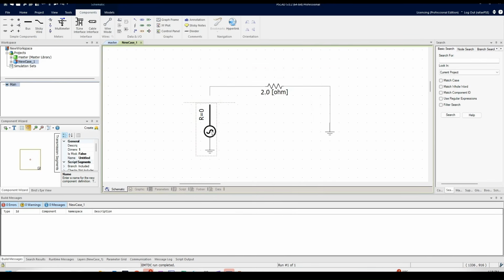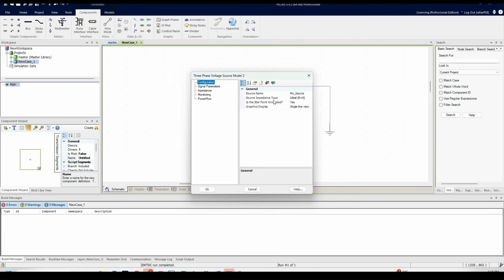And now that single phase line understands that it's connected to a three-phase system as well. It becomes important at one point because there are scenarios in PSCAD where you want to simulate a single line to ground fault, so the fault is only occurring on a single line. So it's interesting. In those cases, you do need to split up a three-phase wire into single-phase wires. We'll get into that. But let's first go into this impedance again and go to signal parameters.